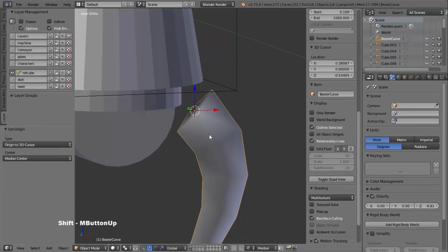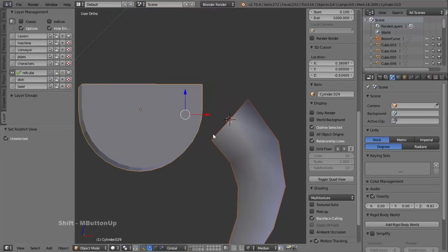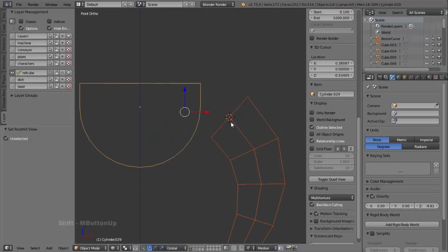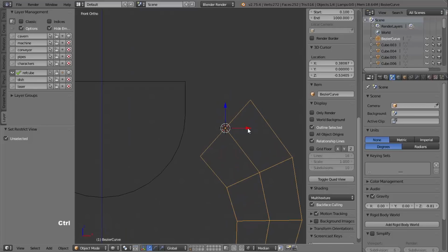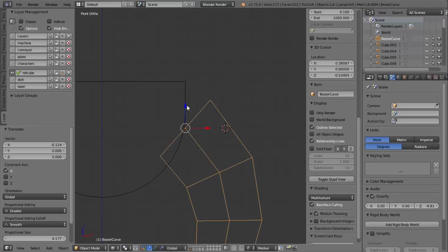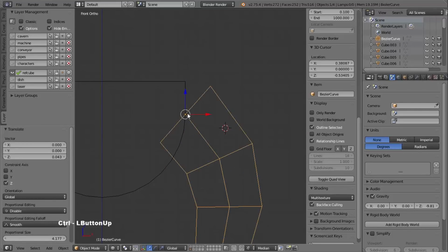3D cursor. So next I'm going to select the hinge object and hide everything else. And I want to snap this object here, the claw, to what was the center of the cylinder where the origin is currently. So back in my front view and wireframe, I want to select the claw, and I'm going to hold Control and then click on the red arrow and then snap it to the nearest vertex. And then I'm going to do the same in the Z axis.